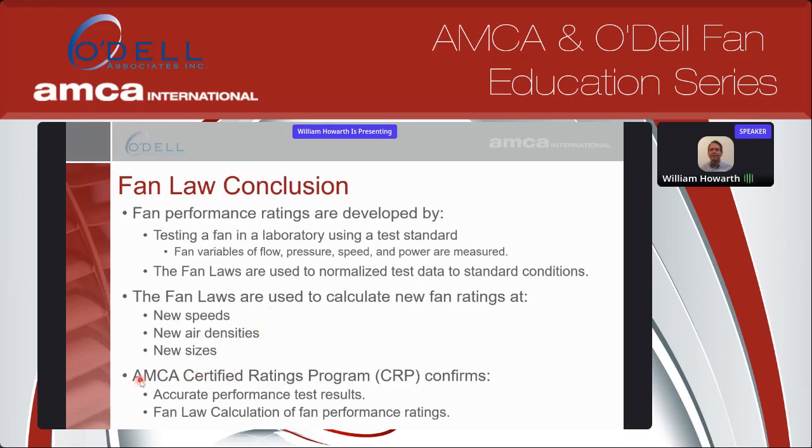AMCA certified ratings program confirms accurate performance test results so that everybody is getting the same results for testing their fan. And then the fan laws are used for the calculation of those fan performance ratings. And you get the same results from different labs, and they're calculated the same way, so you can compare apples and apples within the fan industry.